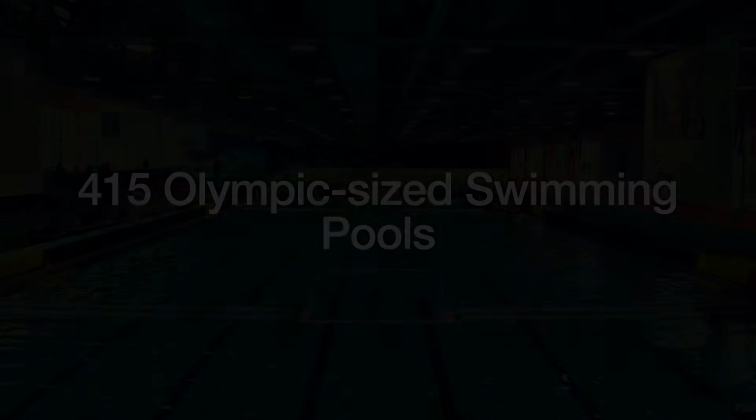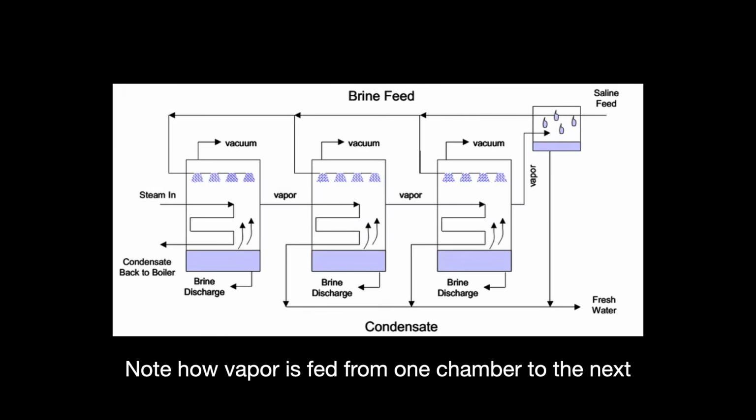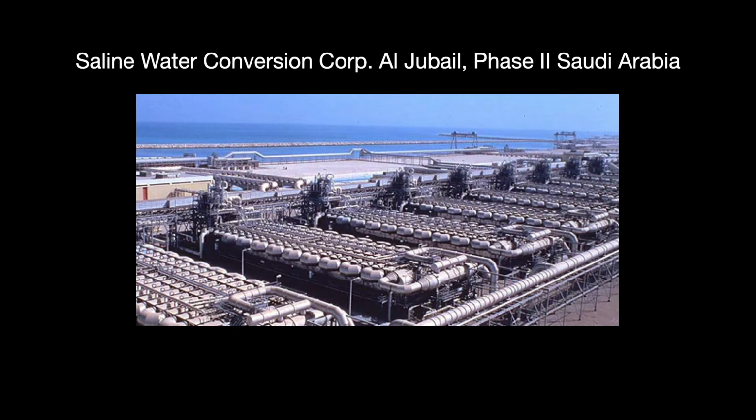The other major thermal process is MED, multi-effect distillation. You have multiple stages, referred to as effects. In one stage, you spray salt water onto steam-filled hot tubes. The heat coming out of the tubes causes the water to evaporate into steam, and that steam then gets fed into the next stage. This heat reuse cycle means that MED is very efficient.